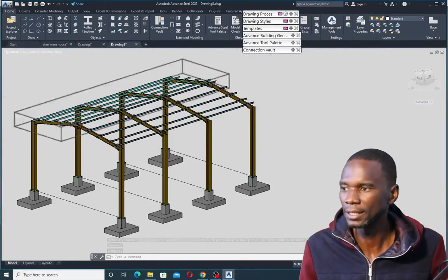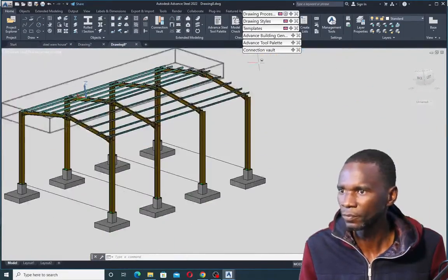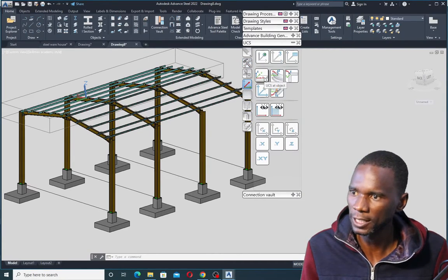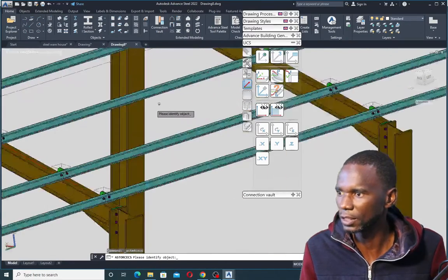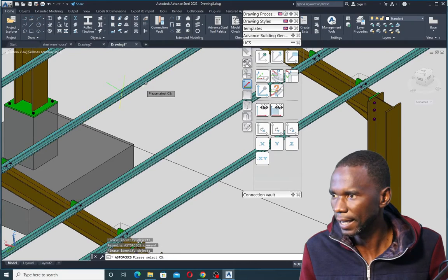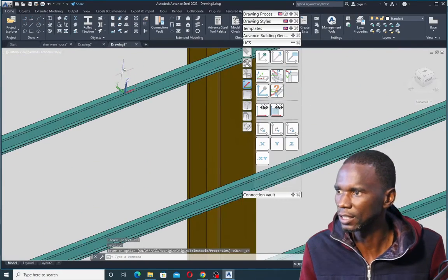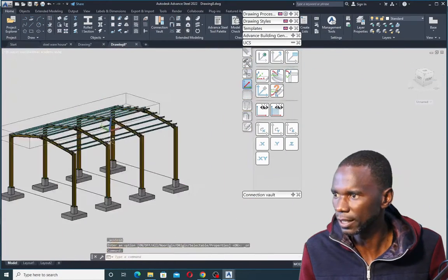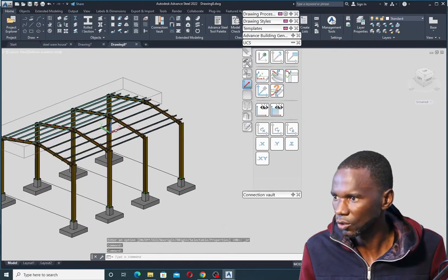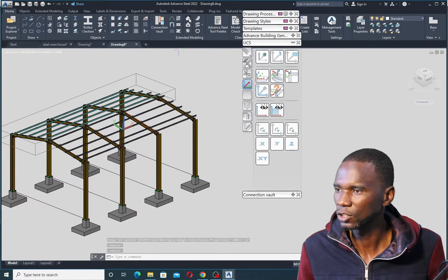And then to create your cladding, you should first of all place your UCS on top there. Then I'll simply go to that tool there, then click on UCS, and I'm going to use that tool, UCS at object, select on it, then zoom in and orbit, and make sure that you pick the top part there, and make sure that you pick the vertical one, just like that. Then right click, then the UCS is right there on top, as you can see. Yeah, it's correct.